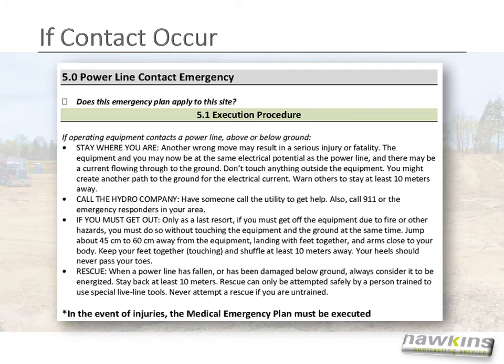Don't touch anything outside the equipment. You might create another path to the ground for the electrical current. Warn others to stay at least 10 meters away. Call the hydro company. Have someone call the utility to get help. Also, call 911 or the emergency responders in your area.